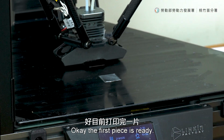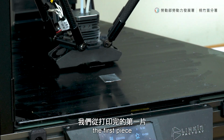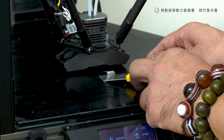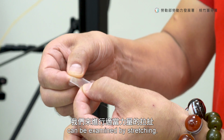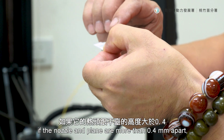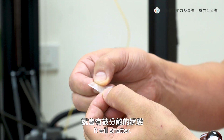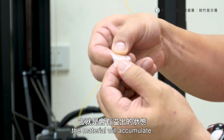Okay, the first piece is ready. The default program prints 3 pieces because we can check the first piece while the machine is running. We can pick it up. Okay, this piece here, as we said, can be examined by stretching. We mentioned that if the nozzle and the plane are more than 0.4 millimeters apart, the material will not be rightly connected. It will shatter. If the distance is smaller than 0.4, material will accumulate.